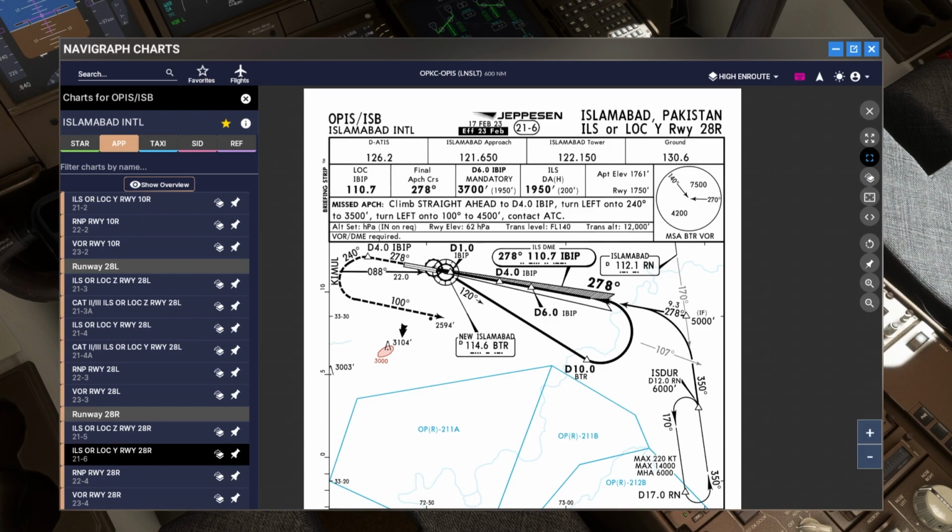Another one, this is basically the decision height for the ILS approach, which is 1950, or 200 feet above the ground. So this is another piece of information that we have to enter in the plane for the landing. What is the decision height? Actually, ILS is an automatic system which takes the plane directly towards the runway, and you are perfectly aligned with the runway. You're going to touch the runway at the exact touchdown point.